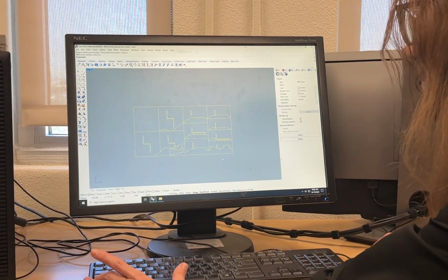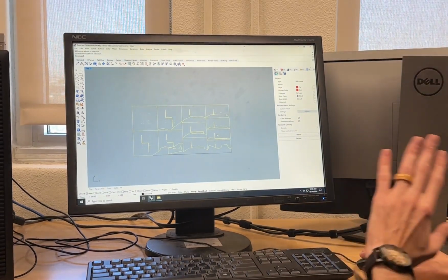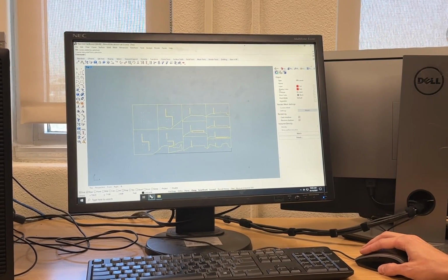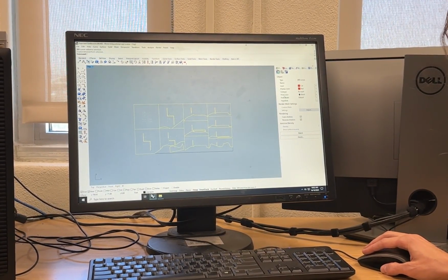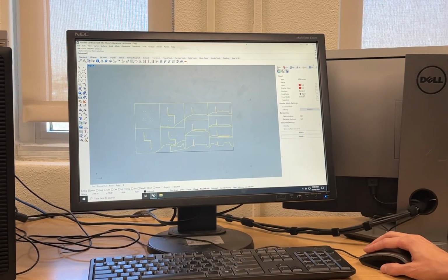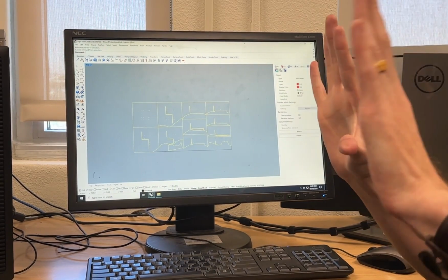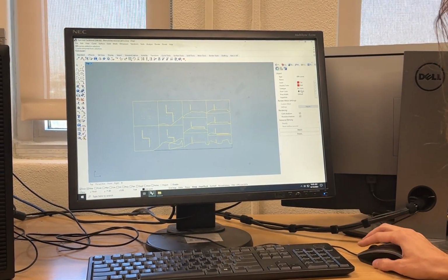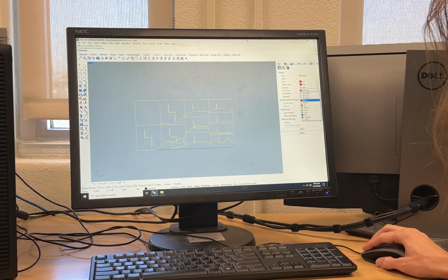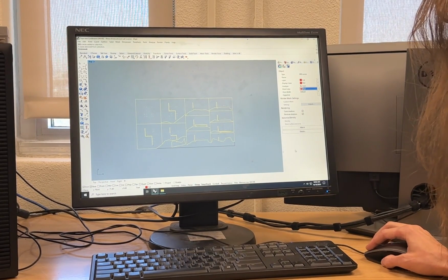In my case, I don't need this outside line. So I'll just get the cut pieces, and as you can see, it just got those pieces. Now, display color, sure, but print color, uh-oh. Remember what I said about this guy? It needs to be a true color, and right now it's set to black, which is why it looked kind of faded in that UCP file. So my print color, even though it's not going to change anything here, I do want to make it red, right? Or again, the color that you need.